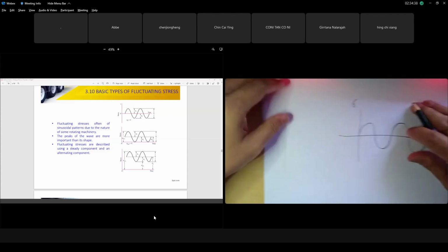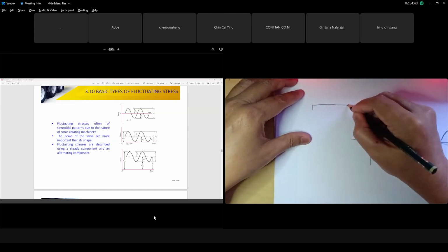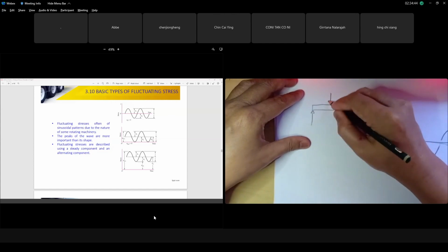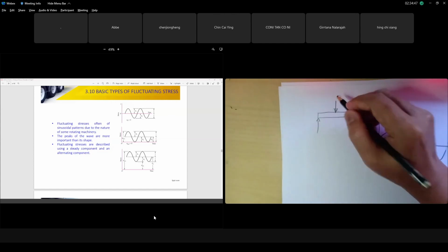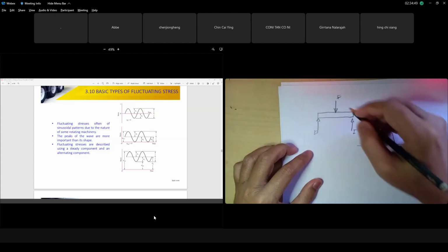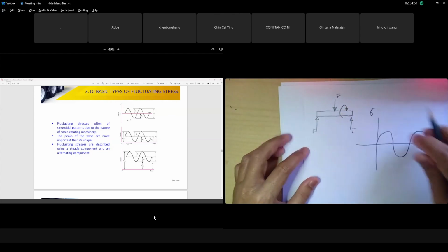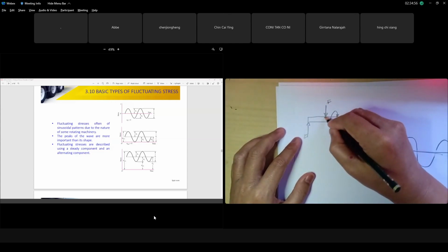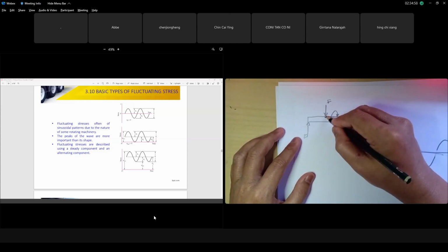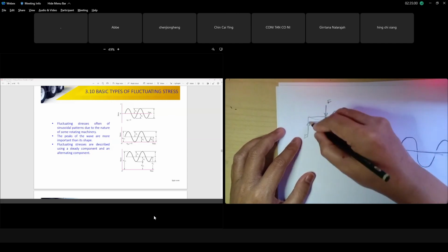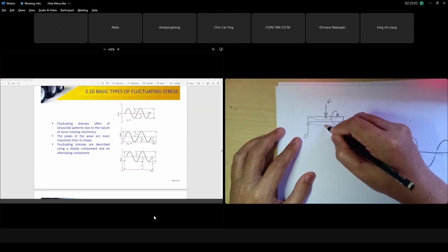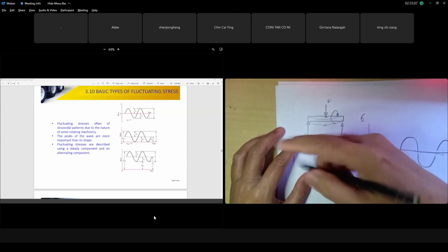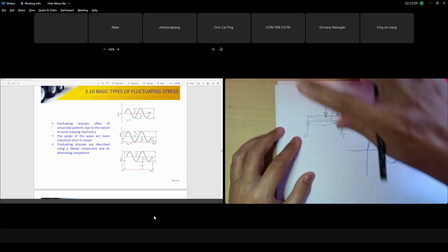Because remember, this is your shaft. You have a bearing support here, and this is your pulley. You have bending and you have a force here. Then you have the force of the bearing, and the shaft is rotating. The shaft is rotating. You can still hear me. So an element at the top here, at this moment, is in compression, right? Because the shaft tries to bend like this. At the top element. When it goes to the bottom, it goes to tension. Top, compression, bottom, tension, compression, tension, compression, tension.